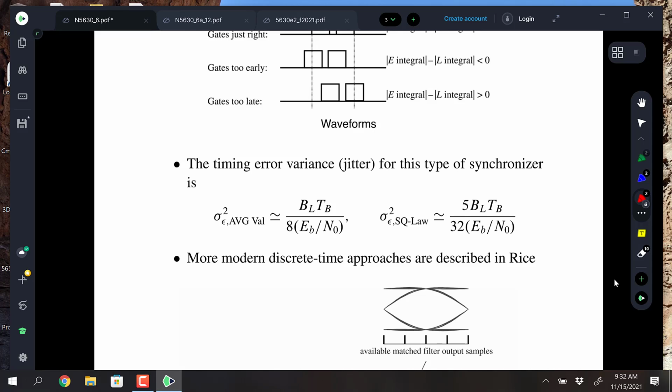And tracking loops also have another bad behavior, and that's called cycle slipping. When the noise gets high, or SNR goes down, the loop will be locked, and then it will go through a chaotic event where it slips a whole cycle. So it will slip out and slip to the left or to the right, and then you lose data entirely at that point because you just had a cycle slip. And carrier tracking loops do the same thing. They slip cycles too. You generally design things so cycle slipping does not take place, but it just happens.